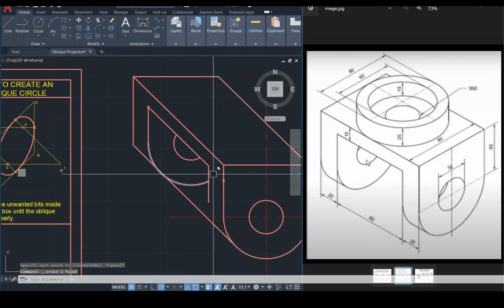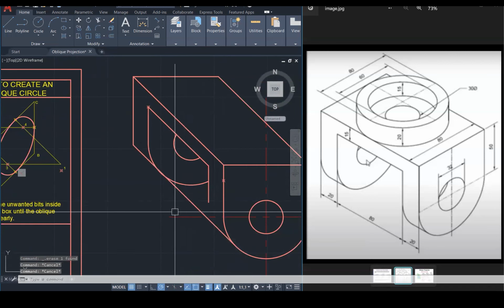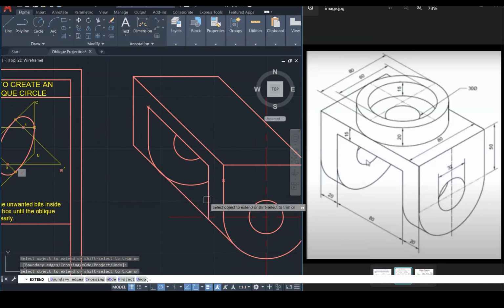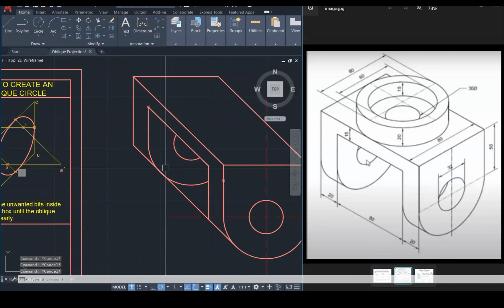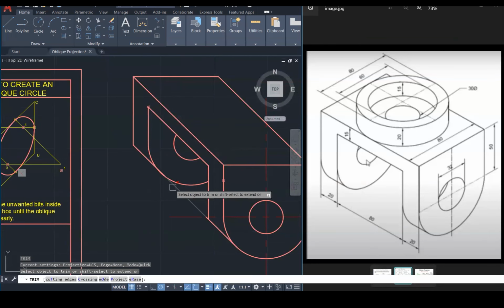So it was a double line that I drew, so I just erased the second line. Now I can extend everything down to that point. That goes down to there. That's in tangent. Now I can trim. If that's in tangent, that's going to do that.